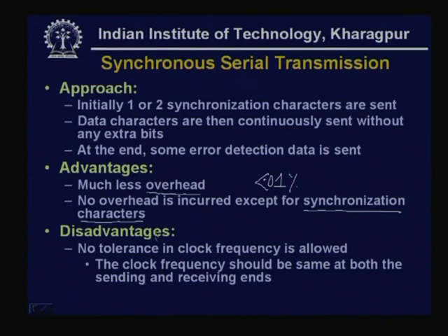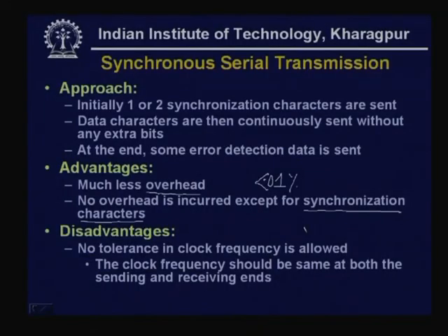However, the main disadvantage here is there is no tolerance in clock frequency. You cannot accept any tolerance, because you are sending a large number of characters. If there is mismatch in frequency, after a few bits the receiving end will receive incorrect data. That is why here it is necessary to transmit in a fully synchronous manner.